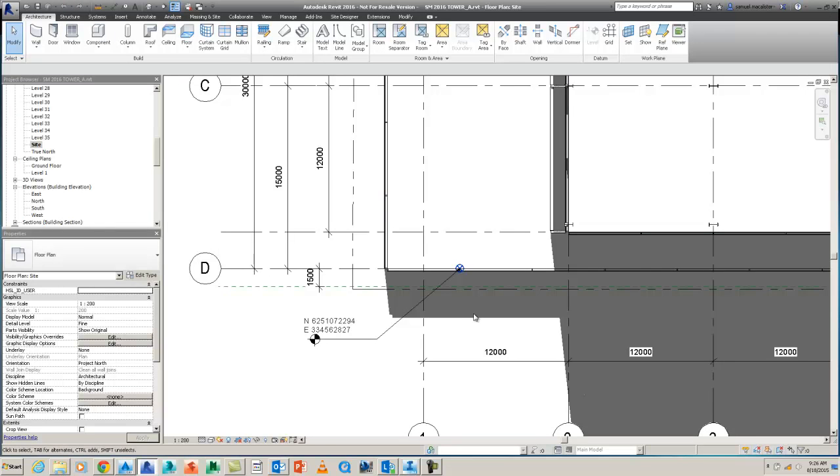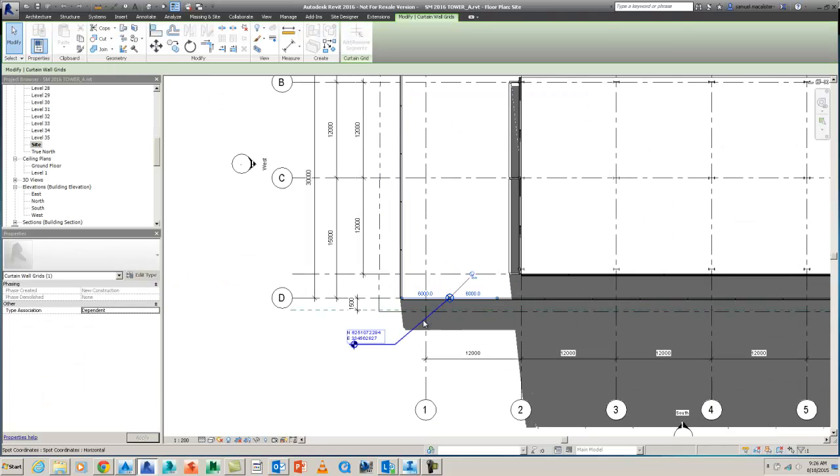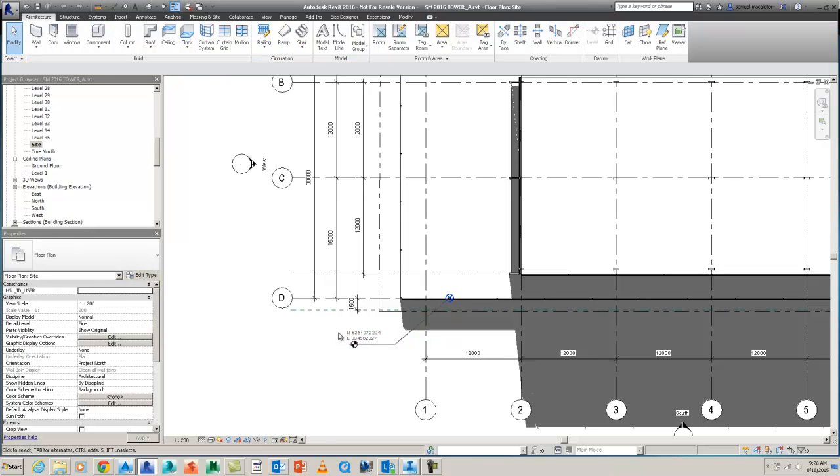What I have here inside of Revit, I've actually set this up with a base point here. This is for the coordinate systems. This is to relate to the northings and eastings that I've got from my setup point and my civil site. There are numerous tutorials on this.